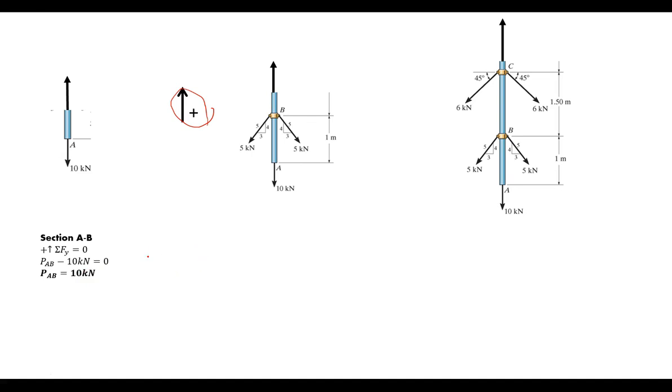The second one is going to be the sum of the forces. This is going to be the sum of the y components of those three forces. So I've got the reaction at BC minus twice the 5 kilonewtons and 4/5 triangle minus the 10 kilonewtons that has to be added in as well equals 0, and the reaction in segment BC is 18 kilonewtons. So we've got 2 down, 1 to go.